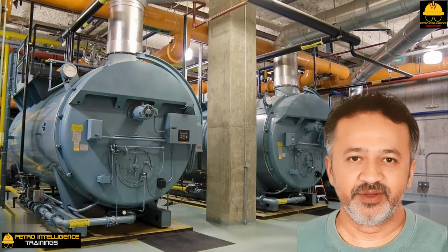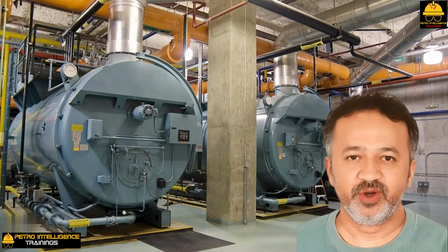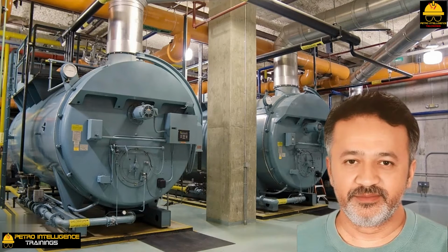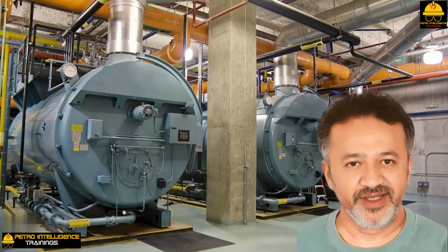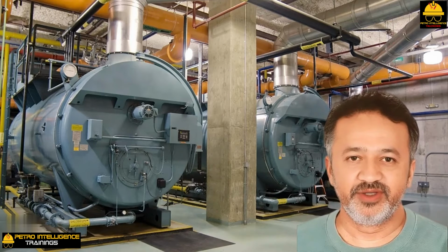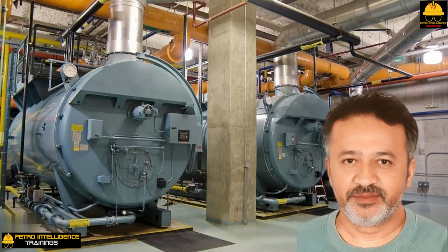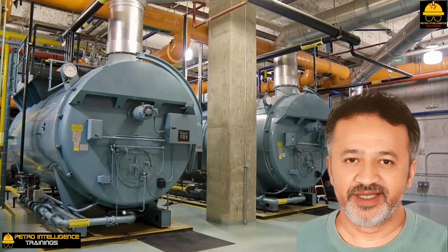Depositing on turbine blades. The deposits eventually get so thick that they break off and unbalance the rotor. Resulting vibrations then cause the turbine to trip off, and stress corrosion of the blades causes sudden failure. Fouling of vacuum system ejector steam nozzles. The TDS content of BFW should be minimized by upstream treating.